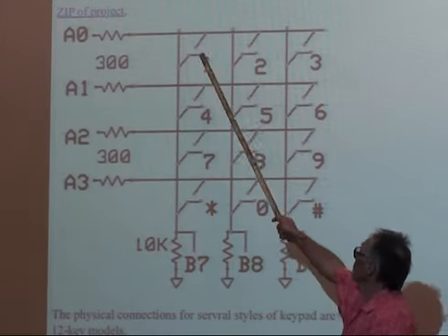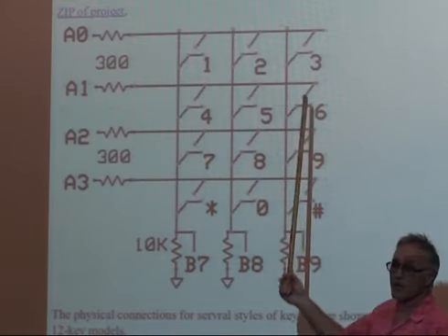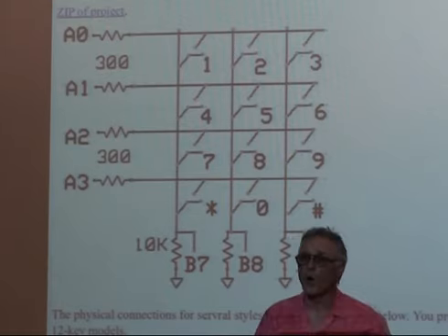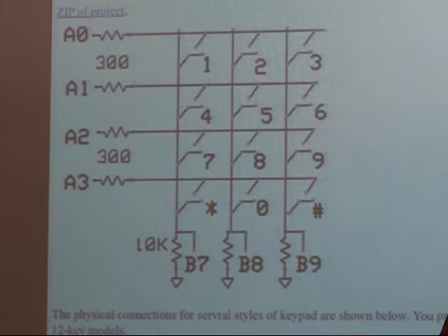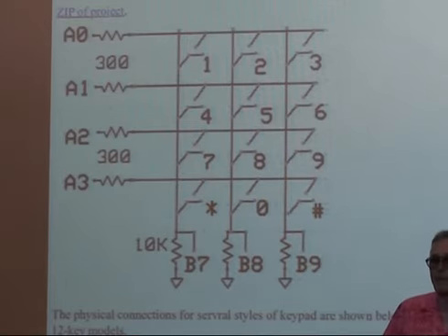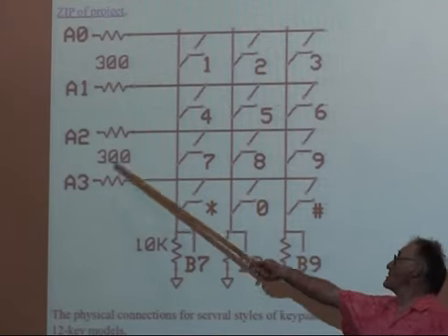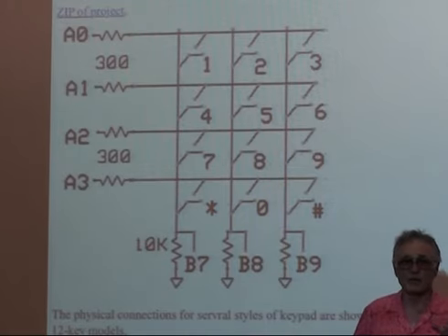You hook pin 1 and 4 together. The node values are less than the CMOS threshold. It never detects a 1, and you get all zeros out. So it rejects electrically the case where any 2 buttons are pressed vertically. If you replace these with diodes, you would be electrically safe, but the lockout, the invalid button push detection, would no longer work.